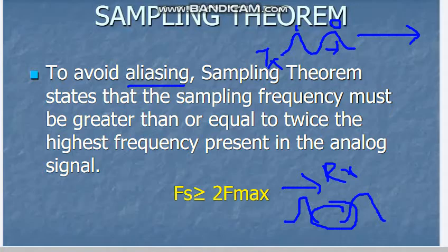Okay, so that's a gap. And another part is just overlapping. In that context, the two signals will overlap each other, and they will miss some data from the point that has been overlapped. So that is known as the aliasing effect in both cases. That is also aliasing, because there is a certain period when no transmission occurs. So that is a problematic scenario, and we have to get rid of that.